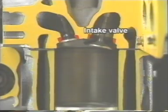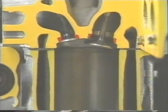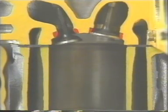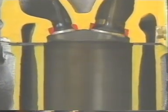The intake valve only has to be kept open while the piston is in the intake stroke. And the exhaust valve has to be kept closed while the piston is in the exhaust stroke. However, valve timing must take into account the fact that the inertias of both intake and exhaust increase as the engine speed increases.